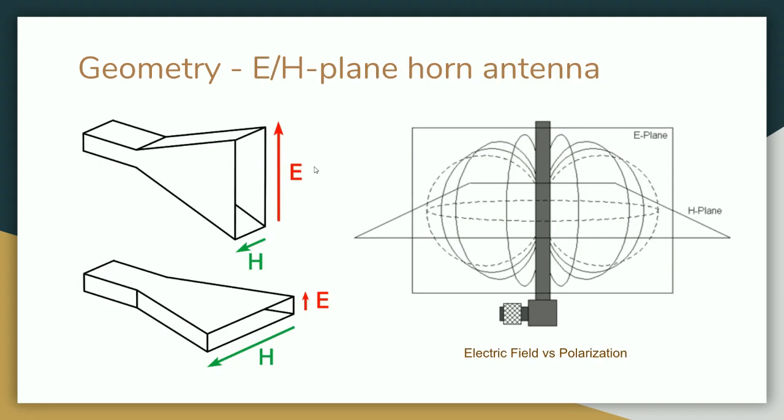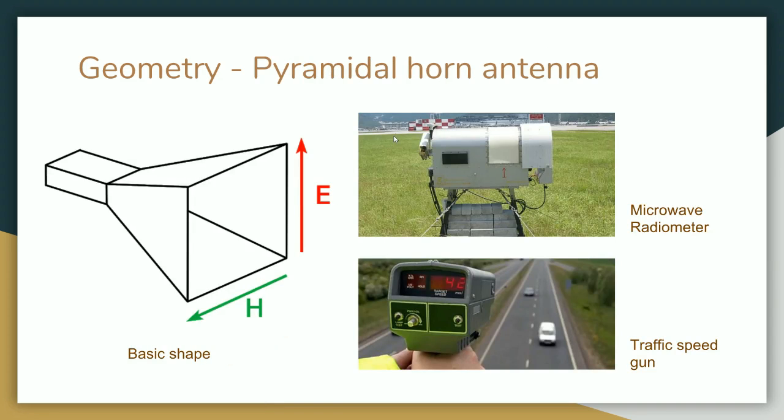The E and H-plane horn antennas contain a flat rectangular waveguide attached to a rectangular horn of the same constant width or length. These flares expand towards the direction of the electric field. The E field determines the polarization/orientation of the radio wave, meaning the vertical/horizontal planes you would use for any applications. So as you can see, the E antenna is used for mostly vertical planes.